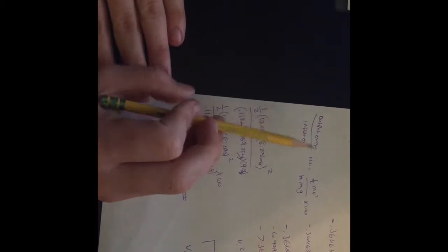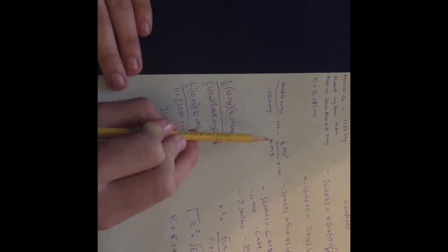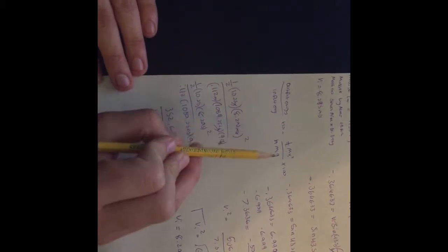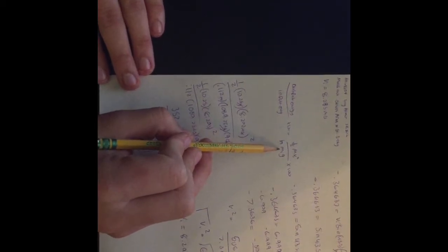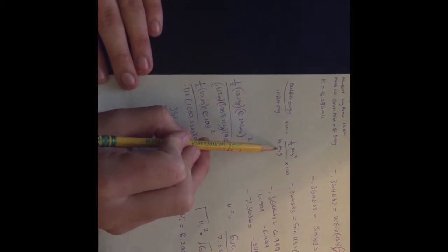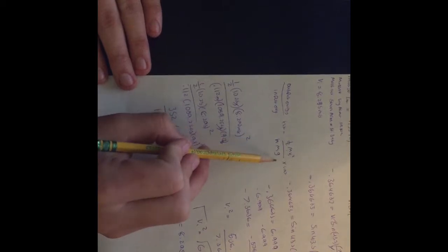And then to calculate the inefficiency, we do output energy, which is the kinetic energy of the projectile, divided by the input energy, which is the potential energy of the counterweight, times 100. So that's 1/2 mass of the projectile times its initial velocity squared, over the height of the counterweight times the mass of the counterweight plus the short arm's mass minus the long arm mass, the sling's mass, and the projectile's mass, times gravity.